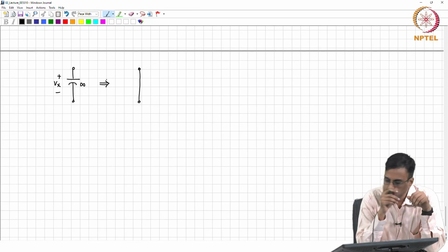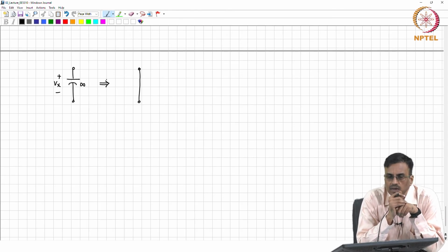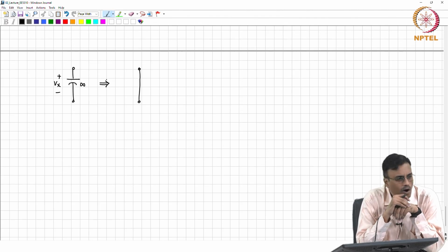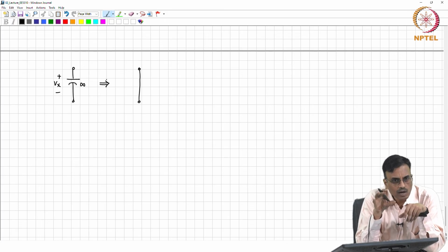So, to summarize our discussion so far, we have looked at what happens when you have a nonlinear network which is general, and we concluded that finding the operating point has to be done numerically. Having found the operating point, a change in the branch voltages and the branch currents can be related to each other using a linear network, and it is not necessary to write out the equations, subtract them, and then come up with a network after all, right.